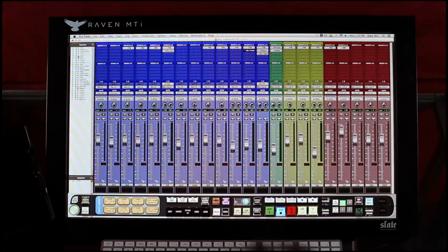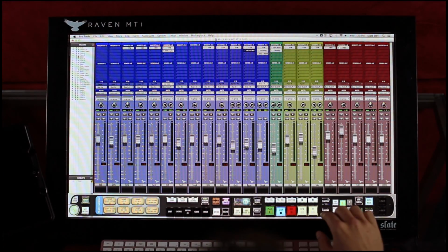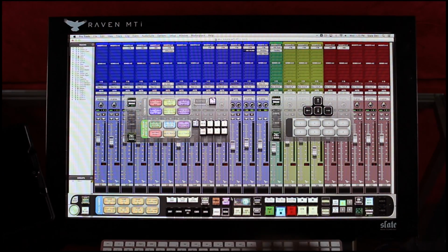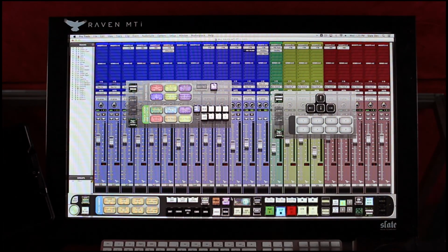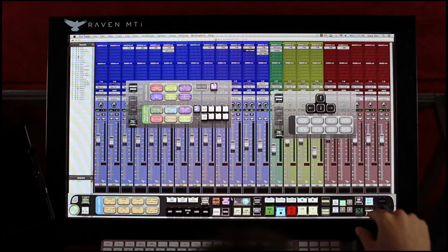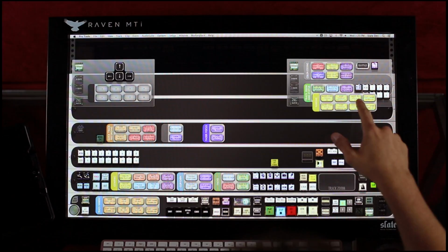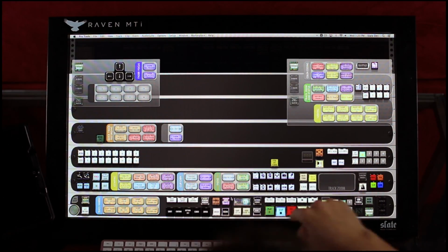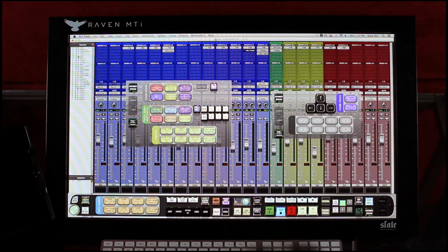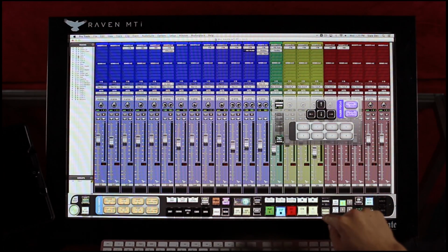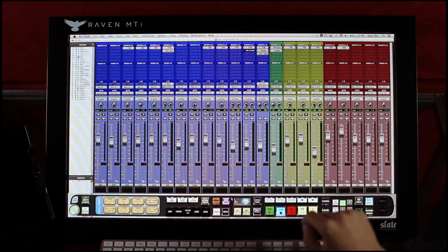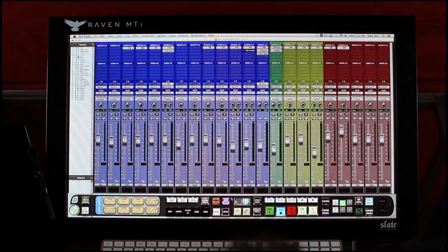In addition to the Raven toolbars, we have also included 2 fully customizable floating tool palettes. The first of 2 is called the Floating Toolbar, and the other called the Essentials palette. Both are designed for adding a select group of tools for managing screen real estate. I can add tools by, again, customizing my toolbar. When the tools are arranged on one or both of my floating tool palettes to my preference, I hit Customize Toolbar again and my layout has been saved. I can then toggle them on and off by hitting the Floating Toolbar, Essentials buttons on the Raven toolbar.